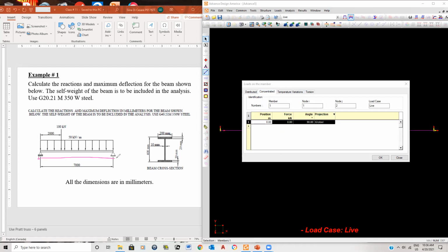then you went there and you click there, well, that's I and that's J, okay? And therefore, the computer will start, whatever information you give here, it will start from this node here. If you happen to click there and add it there, then you're gonna have to go backwards or the other way. So that's why it's important how you remember how you added the member.